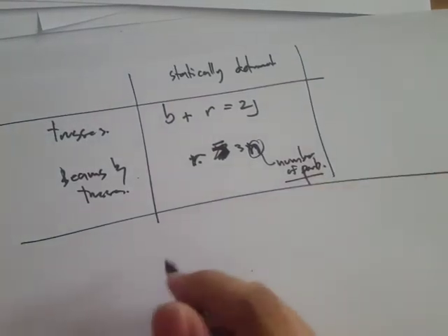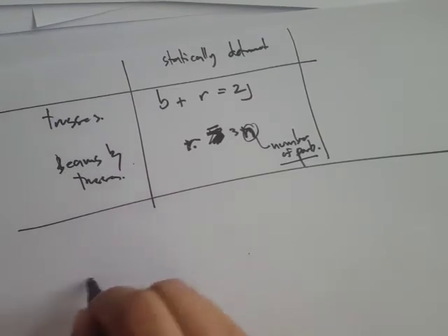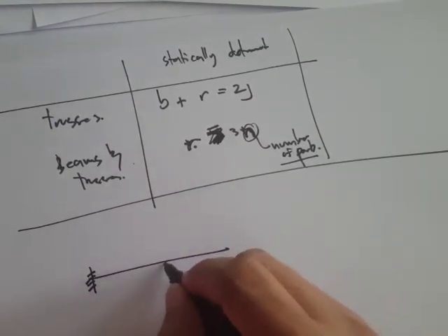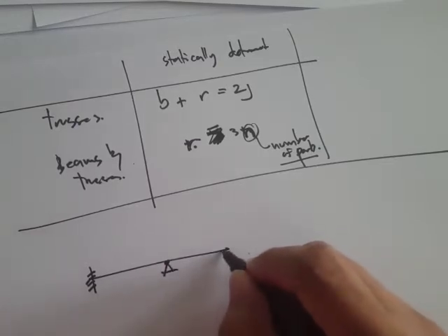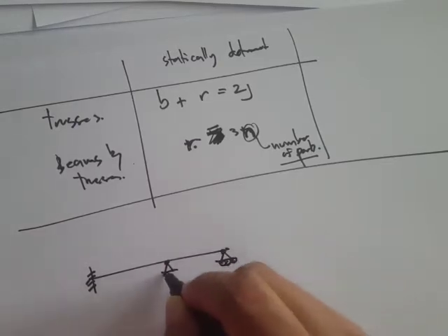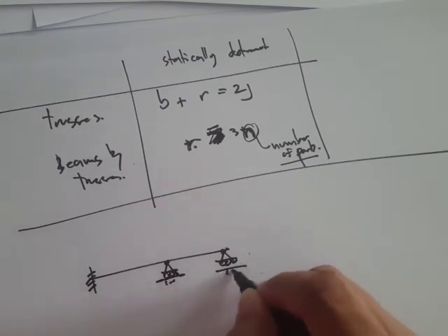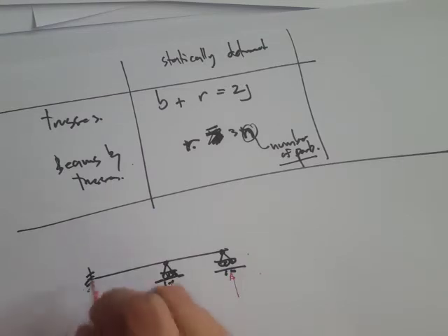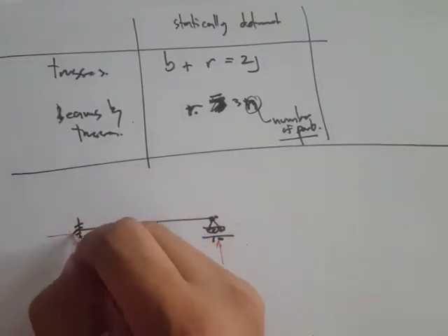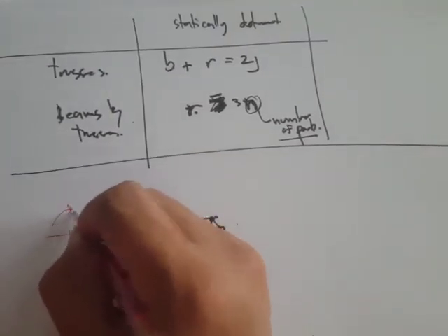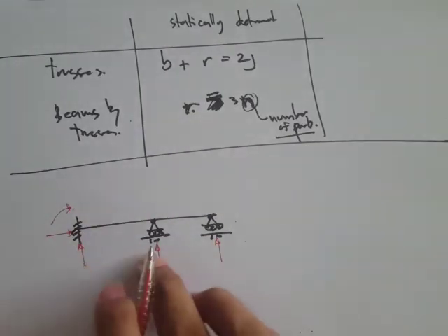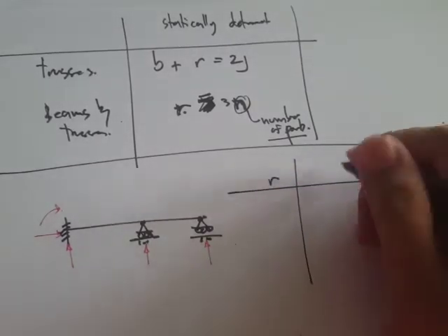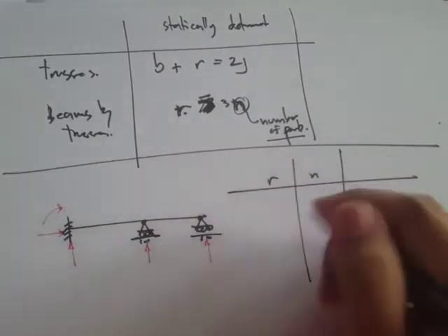Okay, so let's have an example. Let's say for the beam. So if we have, let's say, a fixed beam and then a roller support. Right. So we have, let's say, roller support here. So how many reactions do we have? 1, 2, and then this one, since this is a fixed beam, then that's gonna be, okay, so 1, 2, 3, 4, 5. So the number of R, so let's say Rn, and then our criterion.